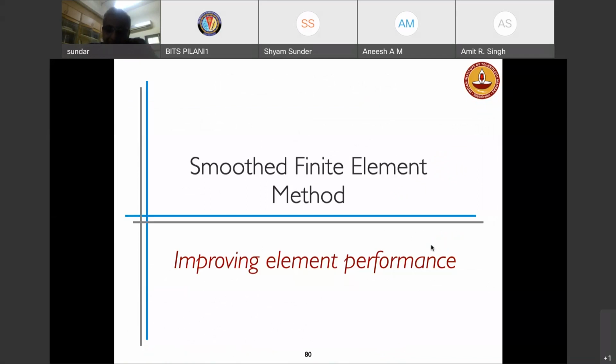So it is built on the fact that we have sophisticated meshing algorithms. We have sophisticated finite element codes which can be parallelized, highly parallelized, right? For example, we have good meshing algorithms like Gmsh, which is an open source software, which can give you 1 trillion tetrahedral elements on a very complicated shape in just less than a minute, right? But we know that tetrahedral elements are really bad because they are overly stiff. They cannot capture the bending accurately. So we need to have more number of elements, which increases the computation power.